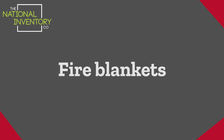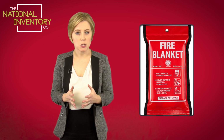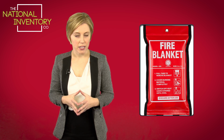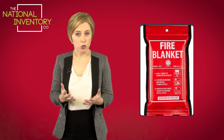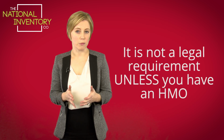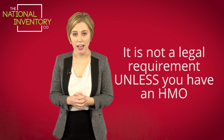Fire blankets. Fire blankets are often located in the kitchen. They should be wall mounted. They must be in their packaging and their packaging must be unbroken. If you do fit fire blankets to a property, you are required to maintain them annually, as you would do with your fire extinguishers. It is not a legal requirement to provide a fire blanket under the current legislation unless you have a HMO.